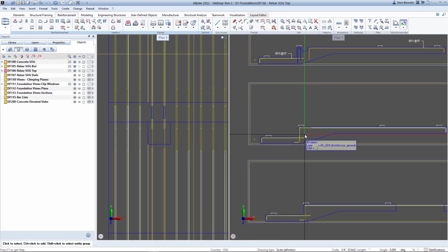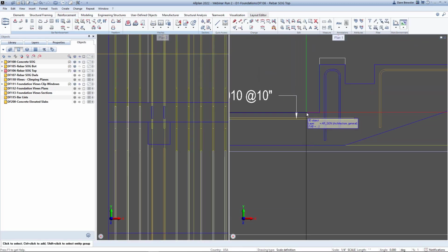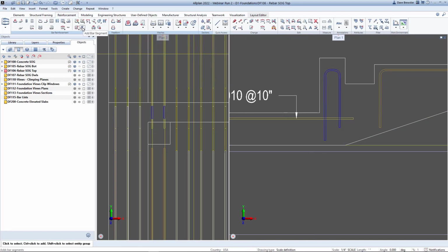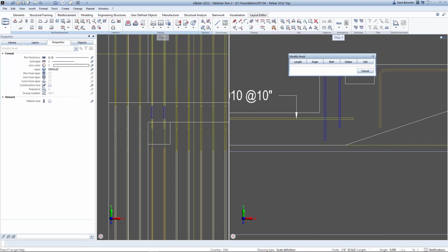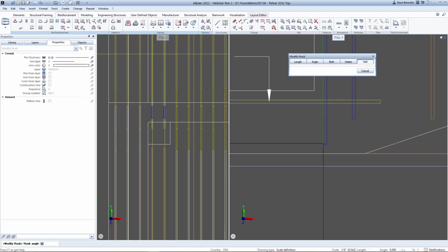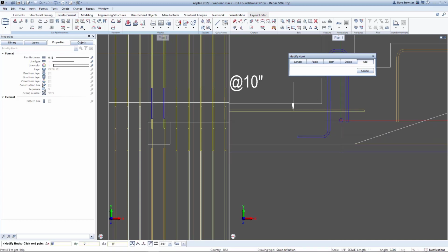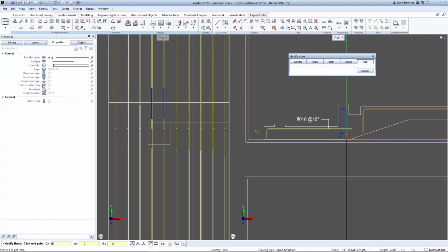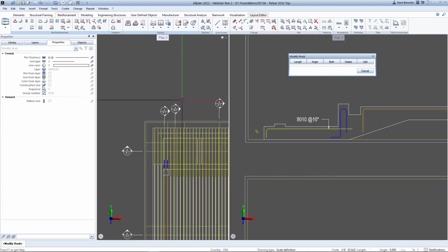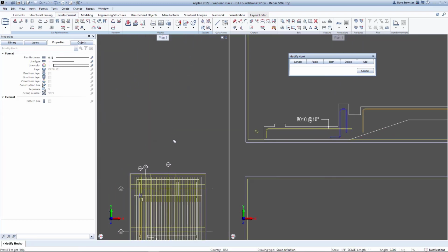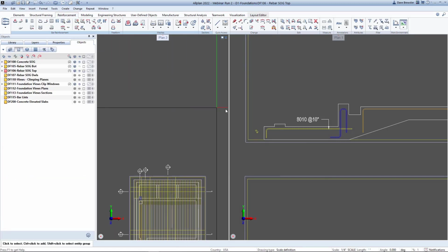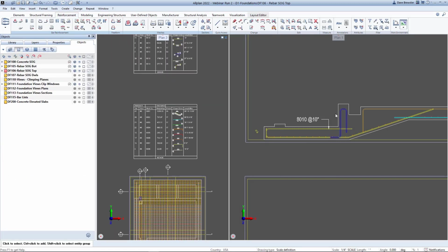I'm going to use a known location from one bar set to another bar set. Again, simple CAD techniques that everyone knows. And now I've generated that bar again over, and it's its own range. So I'm able to pick and choose from existing ranges how many bars I want, and then copy them to another to create new sets. No limitations on that. So all I'm doing here is, I know I needed the hook on this particular bar, so I'm adding a hook to know that we've got enough development past that bar.